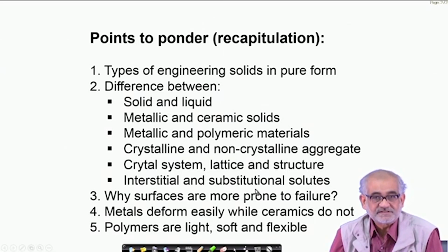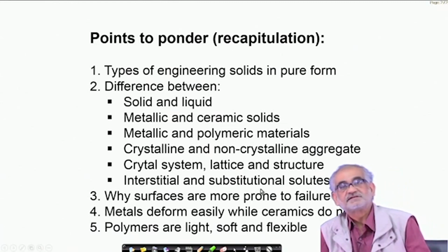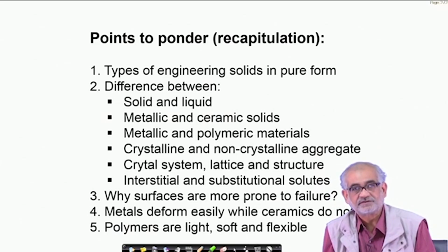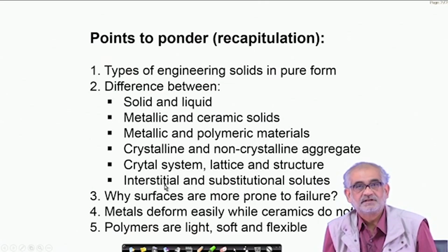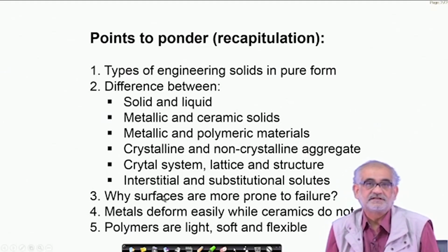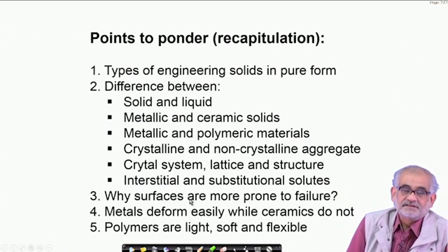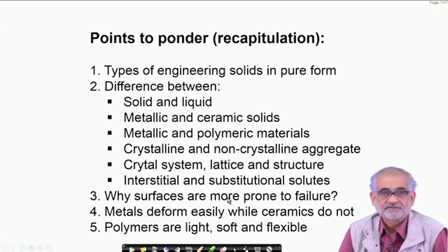We talked about the open spaces available in solid crystals, though from outside we tend to believe that they are impervious and 100% occupied. But because they are made up of these 3-dimensional arrangements of spherical objects or atoms assumed to be hard spheres, we also have open spaces left in the lattice, and they are called the interstitial voids. And we understood that the largest diameter of the interstitial voids can be calculated because the crystal is completely periodic. And we discussed a little bit about the way they are stacked, the way they are coordinated, through which we actually can understand the evolution of various forms of solids.